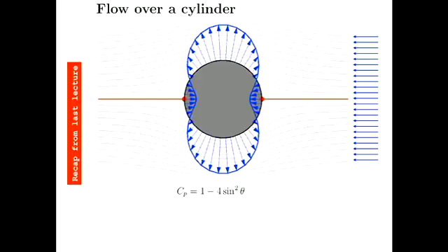So that pressure coefficient is really like a dimensionless pressure force that's acting on that surface, okay? And I know that you come across all these dimensionless groupings and you don't know what possible use they might have. But if I just spoke in terms of the actual dimensional force acting on that cylinder due to pressure, that would be a function of the properties of the fluid, and it would also be a function of the velocity of that fluid, U infinity.